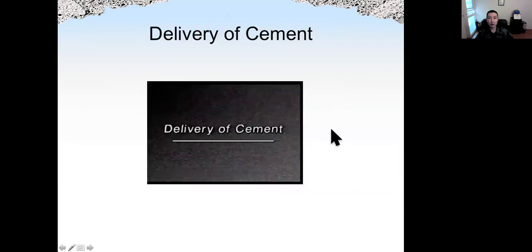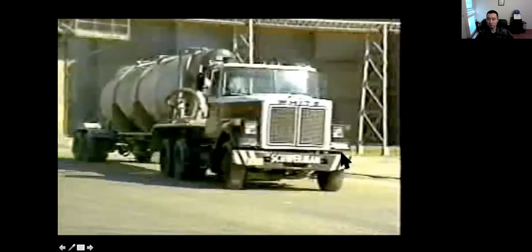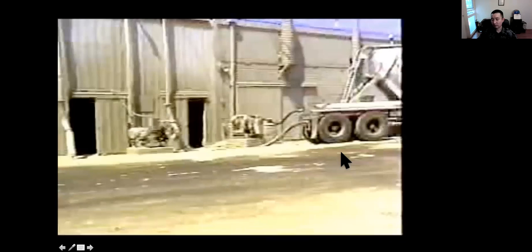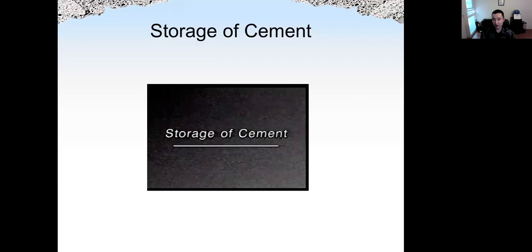Another video about delivery of cement. Portland cement is available as a bulk powder or in waterproof bags. Most Portland cements are shipped in bulk using closed tanker trucks, covered rail hopper cars, rail tank cars, covered barges or ships with closed compartments. Pneumatic loading and unloading of the transport vehicle is the most popular means of handling bulk cement. So there are many different ways to deliver cement, including pneumatic loading, for bulk storage. And also, of course, we can put cement in bags, like we buy the cement in bags from Home Depot.